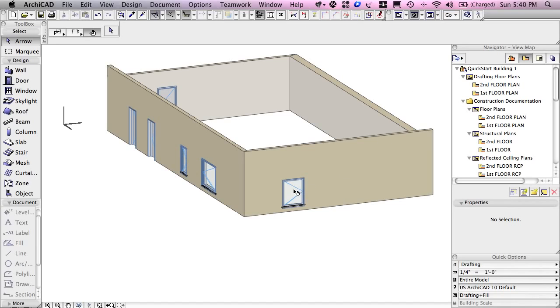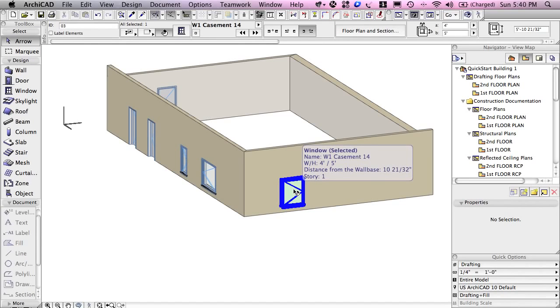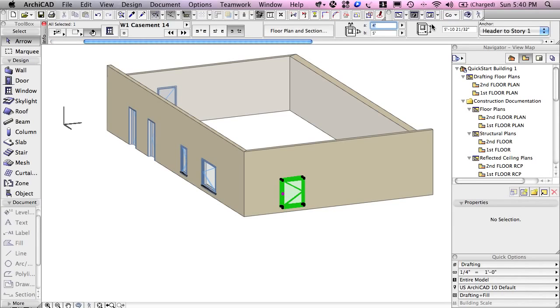Now when I change the size of this window, say from 4 feet to 6 feet, look at how the opening changes. In other words, which way it gets bigger when I change it to 6 feet. You'll notice that it got bigger only in one direction, because you may recall in the earlier module I placed it by this corner. In other words, I anchored it and said this corner is important, create a window starting from that corner. So that anchor is very important.